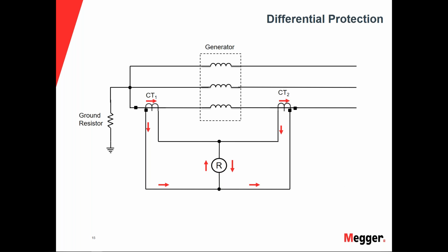When we do have an internal fault and the relay sees it, then this generator is going to be feeding into this fault. And when the generator feeds into the fault, we will get a reversal from the current coming back from the transformer, or the unit or breaker transformer combination that's over here, back into the system.